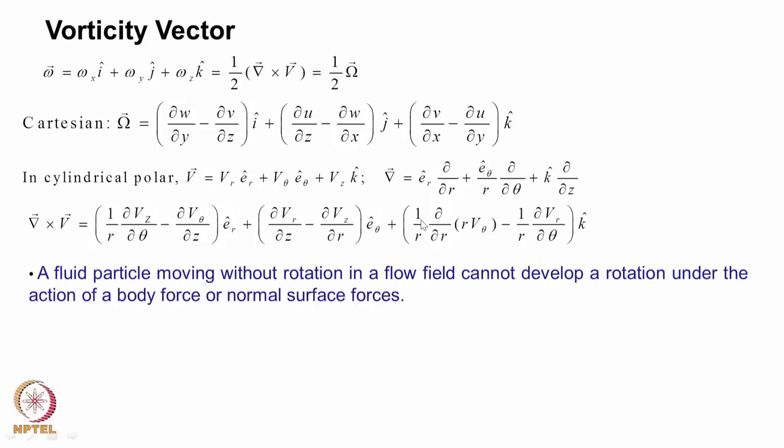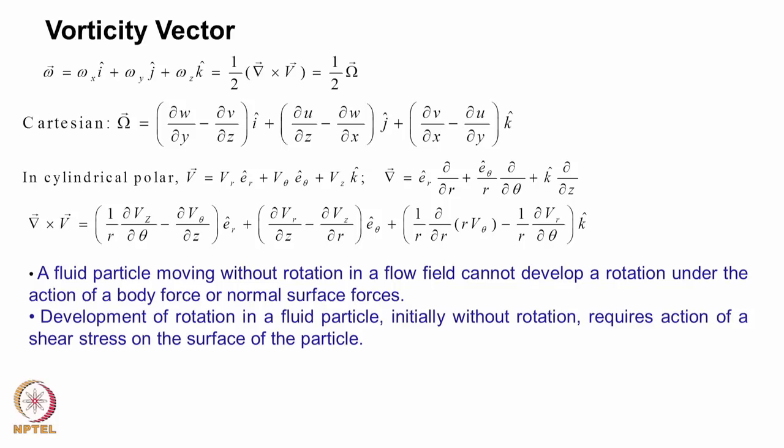Now, we know a fluid particle is subjected to body force or normal force as well as shear force. A fluid particle moving without rotation in a flow field cannot develop rotation under the action of body force or normal force. Development of rotation in a fluid particle initially without rotation requires the action of shear stress on the surface of the particle.